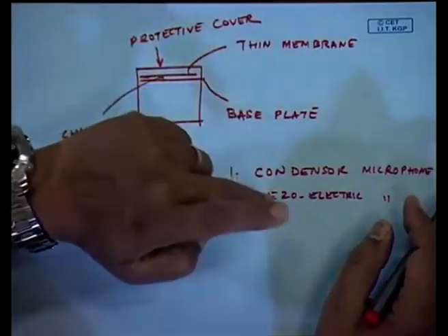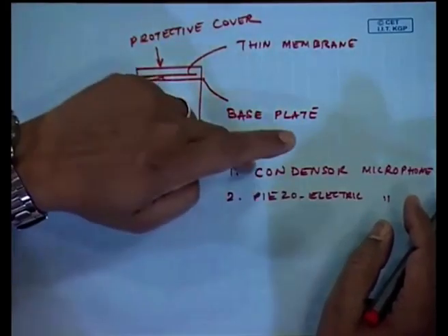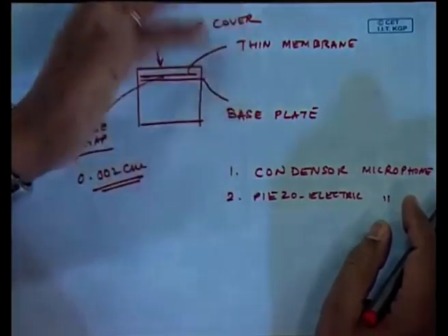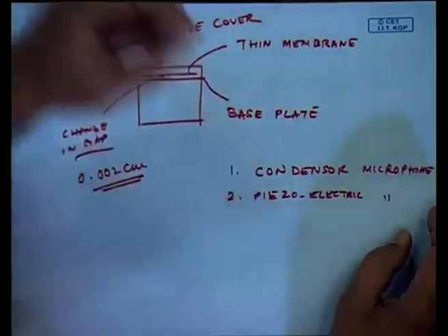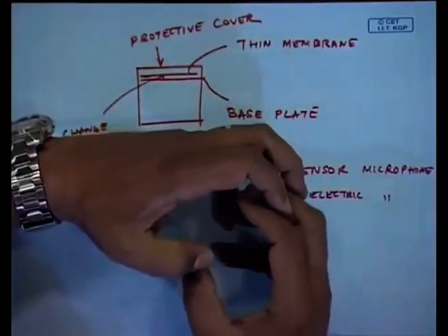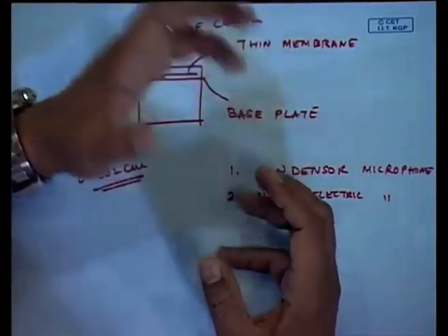Now, the difference between a condenser microphone and a piezoelectric microphone is that condenser microphones can practically last forever, because there are just two metal plates. But piezoelectric microphones will lose their sensitivity, because the piezoelectric crystals could age, since they are exposed to the elements. In the case of the sealed accelerometers, the piezoelectric crystals were sealed forever. They were not open to moisture or air and so on.